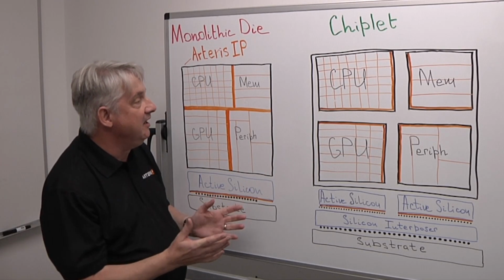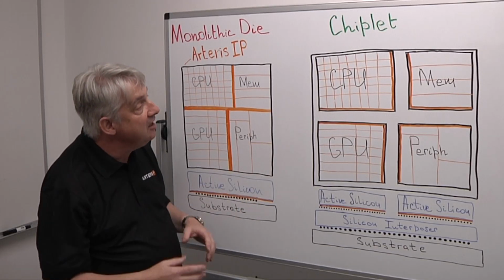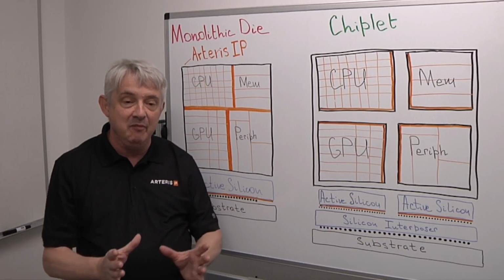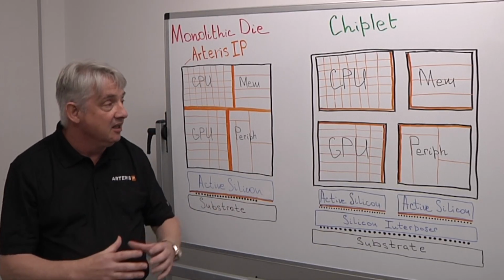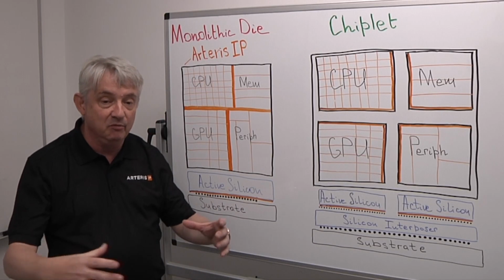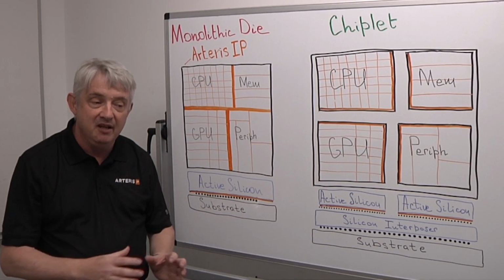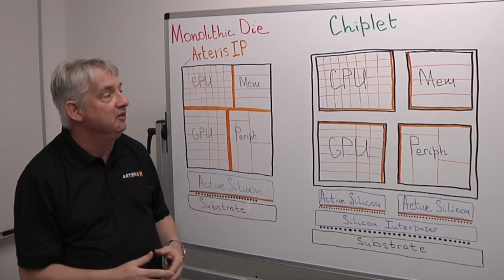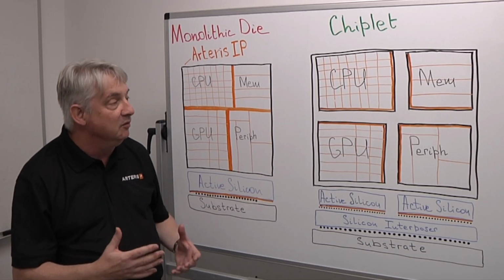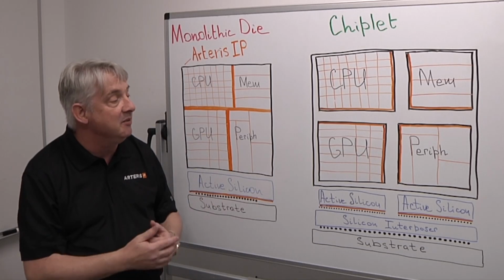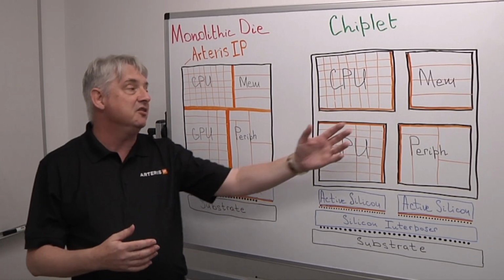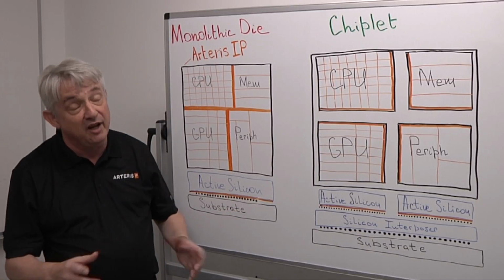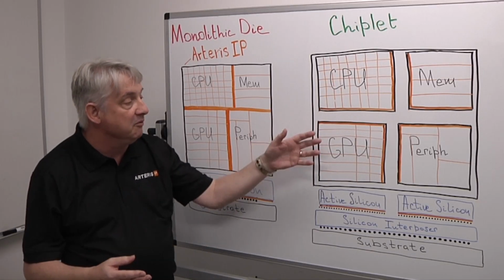Yeah, I mean, it used to be in the early days, not so long ago, that the cost of a wafer was basically the same in terms of per millimeter squared. You got more transistors on a smaller geometry, but the overall wafer cost was the same. Well, that is not true today. The cost of wafers has gone up exponentially on modern processes. So that means it's very wasteful to be developing something like analog that you mentioned on a modern process. And we also mentioned memory, where again, it doesn't scale beyond 5 or 7 nanometers. So it's very wasteful if you have a lot of memory to use a very modern process.